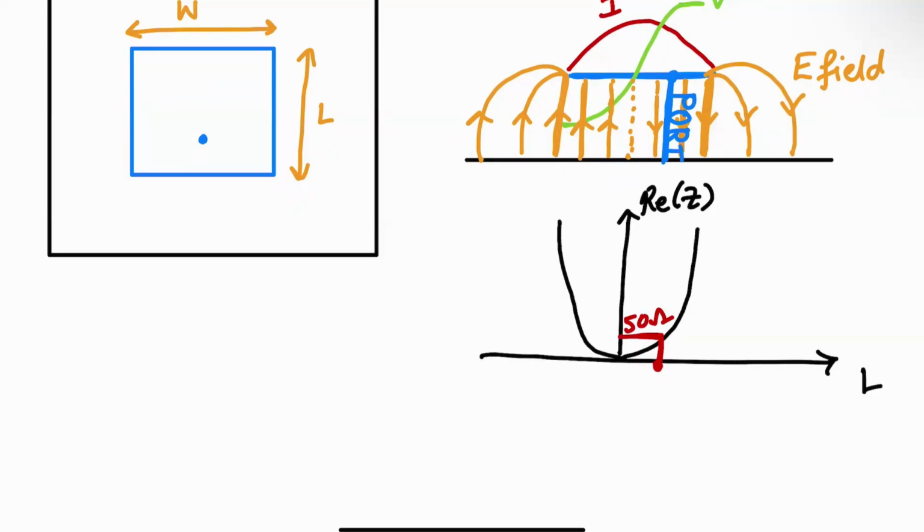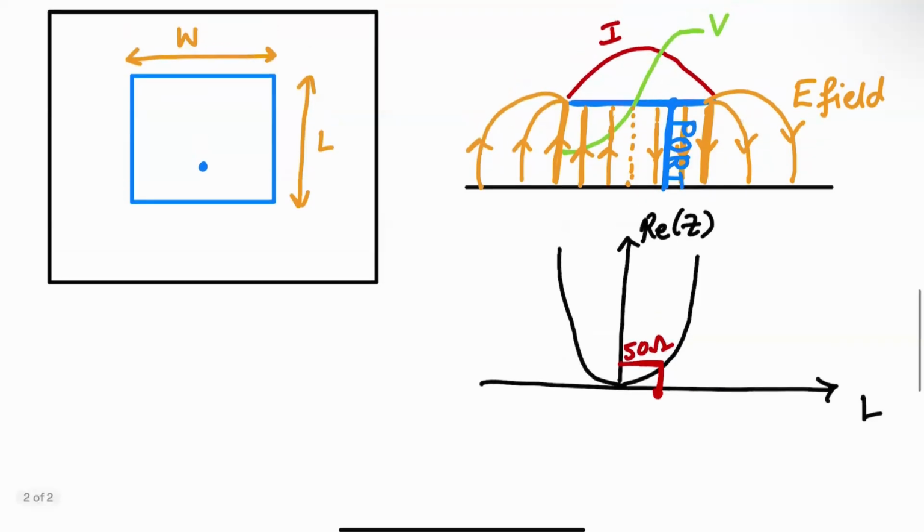All right. So there are many ways to model a patch, to analyze a patch. So I think the simplest way is just to give you some intuition as to what that looks like. So we have a current on this surface and we have another current on this surface. And they are usually in the opposite direction. So the current on the patch itself doesn't really radiate, right? There's actually very weak currents on the top surface. You don't see much current on the top surface. You can plot it in HFSS and see that. So if you look on this side, you'll only see some current on the sides here.